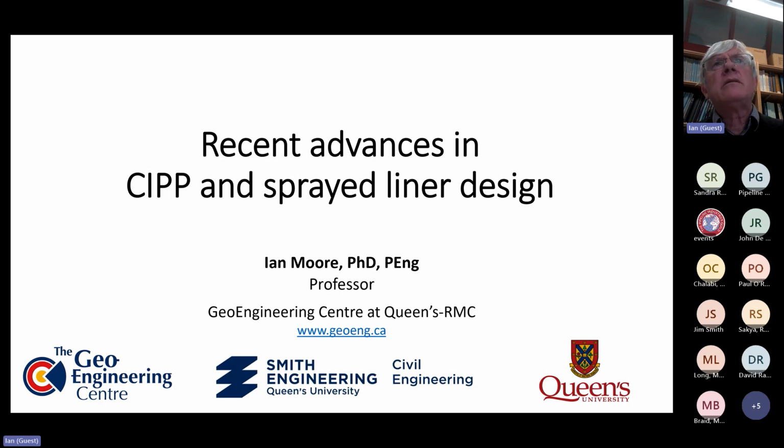So then there are techniques, and there are other publications if people are interested, that I haven't talked about today, where you can go from the free field ground motion to estimates of how much rotation and axial extension you'll get at specific joints. And typically we clump all of the rotation that we might expect along a certain segment of pipe, let's say halfway along one barrel, past a joint to halfway along the next barrel, and we clump all of that rotation and all of that axial extension at that joint.